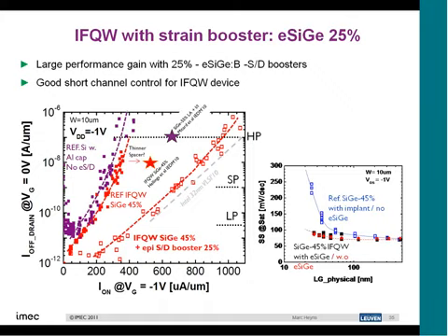This is the off current, which is a typical benchmark. If you look to the red curve here, which is the implant-free quantum well germanium device that we make, it compares, I think, very well with the very best devices that Intel has been publishing last year at the VLSI symposium. So I think this is a very, very encouraging result. It also shows you that the subthreshold slope actually is maintained even for very short channel lengths, indicating that we have a very good electrostatic control of these devices.